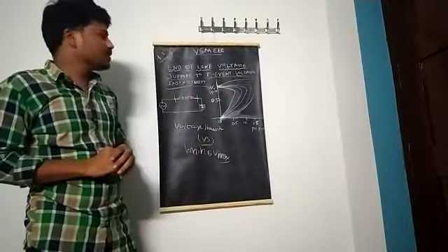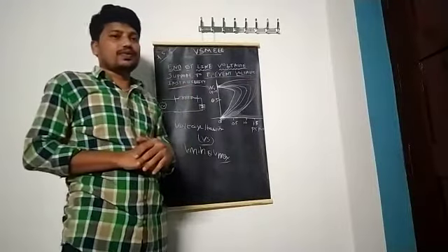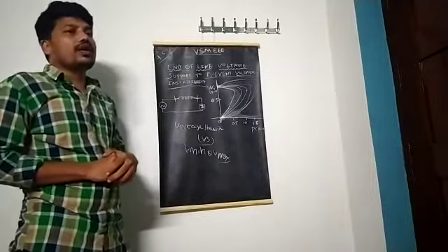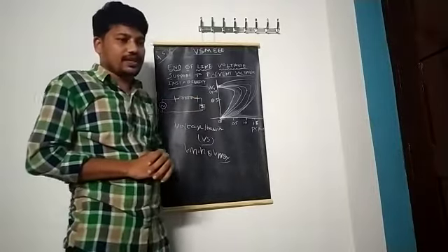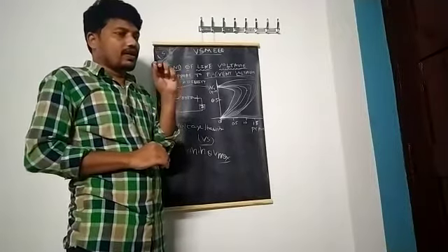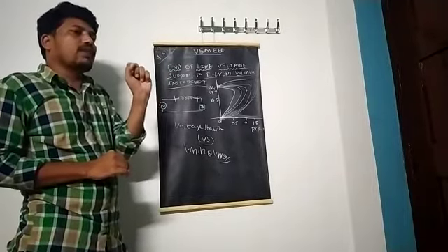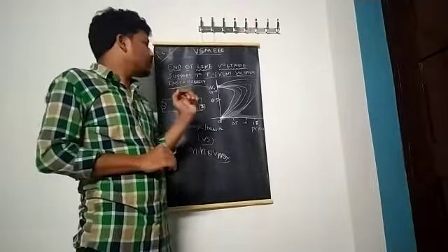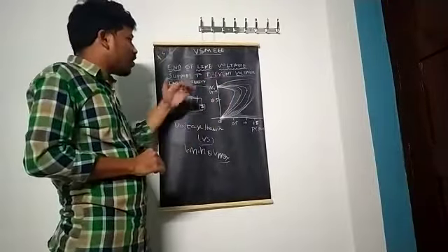From this knowledge, we can observe that voltage instability is one problem which occurs severely in power systems. So in order to prevent this voltage instability problem, generally we go for the compensation technique. In the previous class we discussed midpoint voltage regulation, in which we discussed shunt compensation. Again we studied how the compensation can improve the active power and the real power. Similarly, the same compensation technique can also be adopted here.